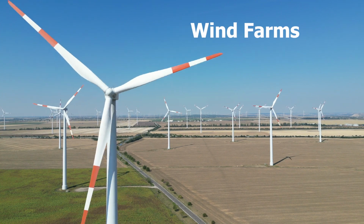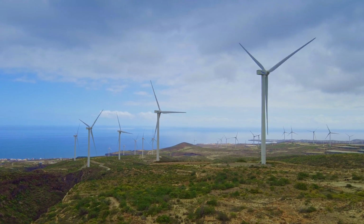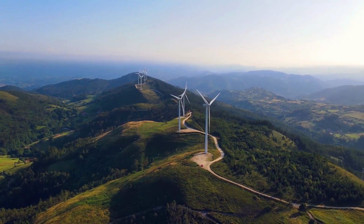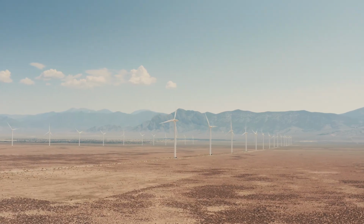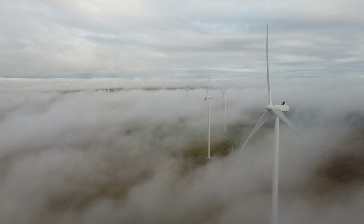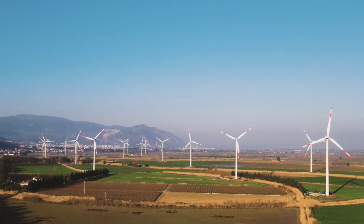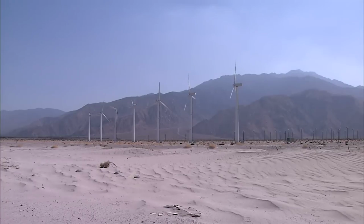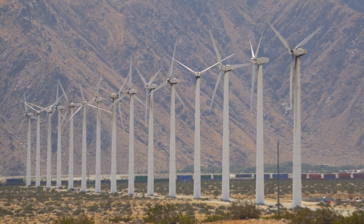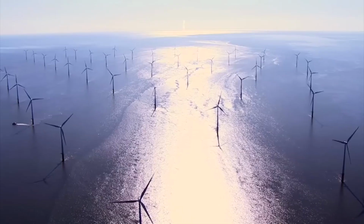Turbines grouped over a large area are called wind farms. Wind farms provide power to the electricity grid of large-scale utility companies. They can either be on land, known as onshore, or on oceans and seas, known as offshore. Most projects today are onshore. Onshore wind farms require a turbine-to-turbine separation of 7 times the diameter of the rotor. Therefore, wind farms require a large acreage of land space. For example, the largest onshore wind farm in the United States, the Alta Wind Farm in California, has 600 turbines in an area of 3,200 acres or 5 square miles of land.